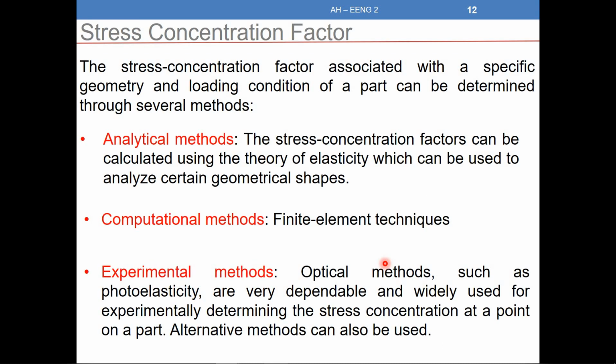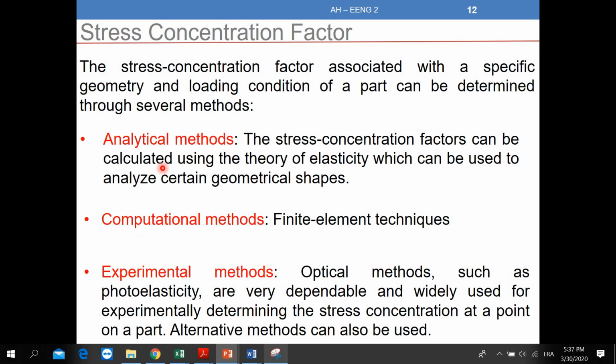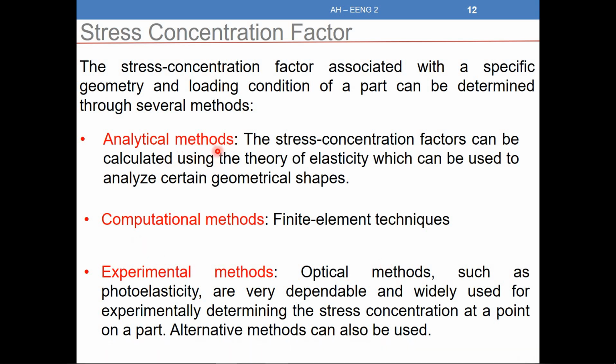Now, how do we calculate the stress concentration factor? Just to understand, we have different types of methods. We have analytical methods, where we do calculations based on the theory of elasticity, which means the stress tensor, the strain tensor, and the relation between them. Computational methods, like finite element techniques, use computer software like the ones that we'll be using in the practical work. And there are also some experimental methods that are used depending on the geometry. All these methods are used to find the stress concentration factor in the presence of a hole, a notch, or a fillet.